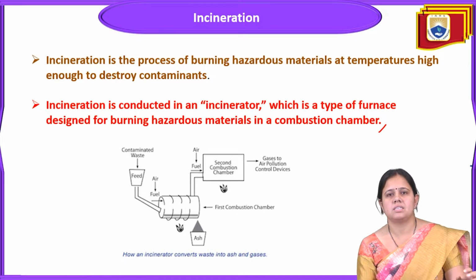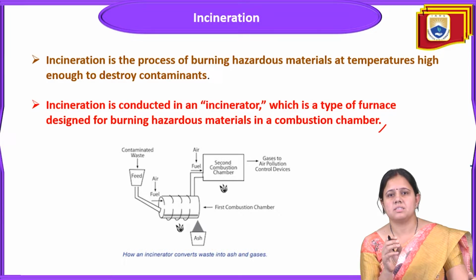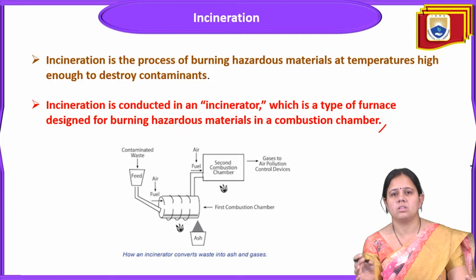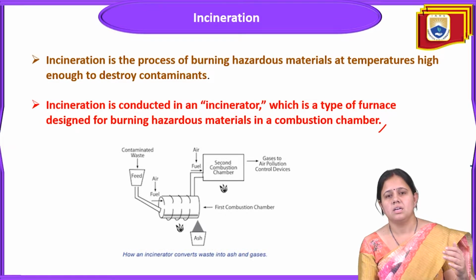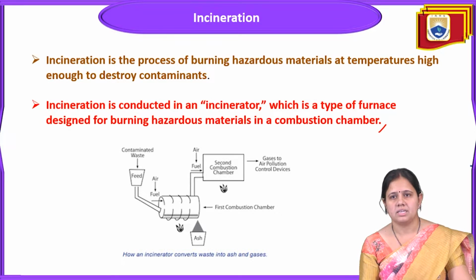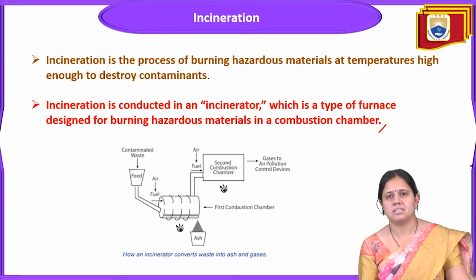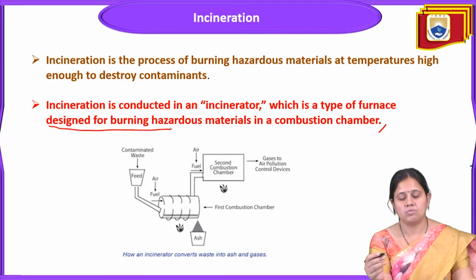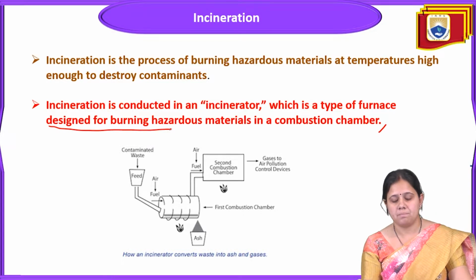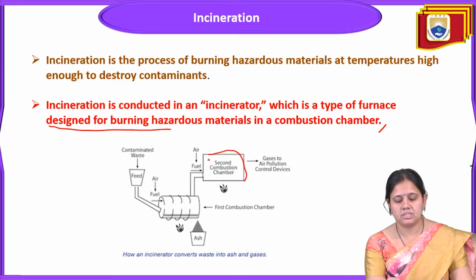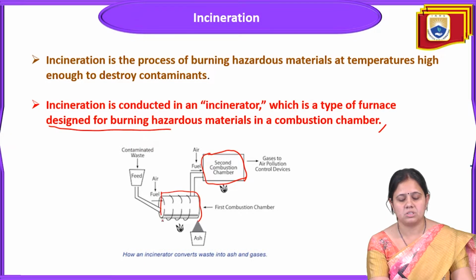So basically this incinerator is used for hazardous waste, so that the contaminants in the hazardous waste will be burned out, and in this way it will destroy all the contaminants. And it is conducted in an incinerator. An incinerator is a kind of chamber, or a kind of furnace, designed for burning hazardous material in a combustion chamber. You can see these two types of combustion chamber.